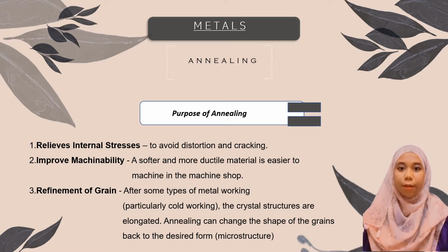There are several purposes of annealing. The first one is to relieve internal stresses. By annealing, it helps to avoid distortion and cracking of the metals. Second, it helps to improve machinability. A softer and more ductile material is easier to machine in the machine shop.